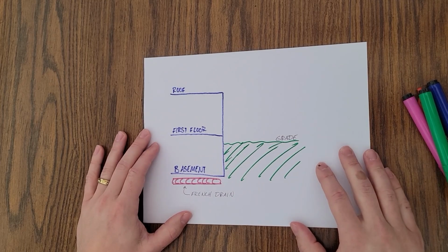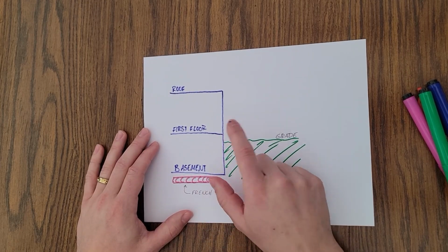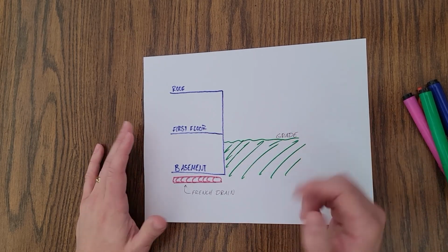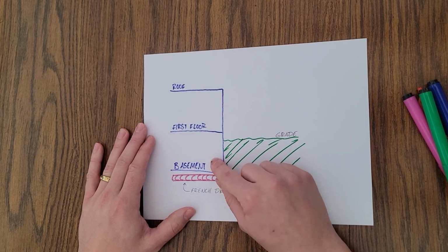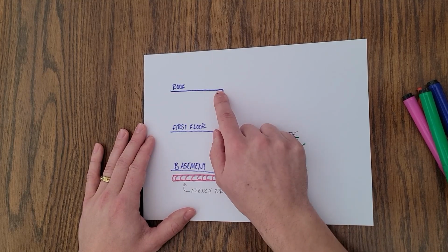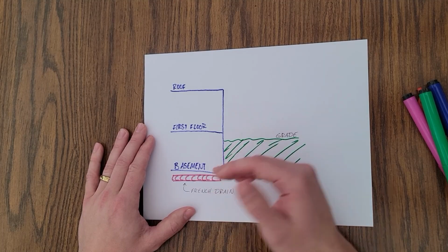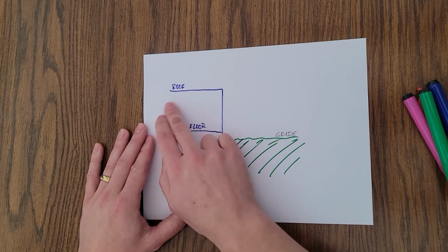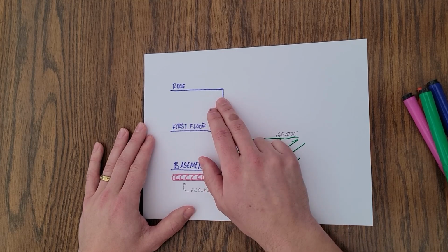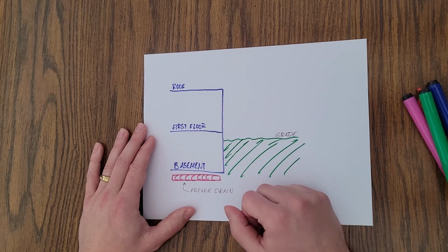What we want to do now is lay out the route our piping is going to take up to our fan and then past the roof. Most states, I'd probably say all states, require that the radon air sucked up from beneath the slab is discharged above the roof. That is so that none of the air has the potential of getting back into the home. So it's discharged above windows and above soffits that are part of the exterior of your home, so no air can go back in.